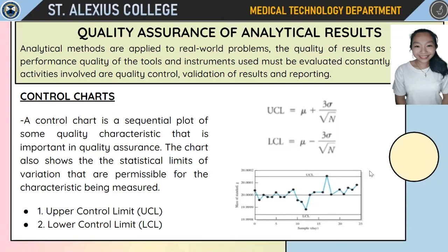A control chart always has a central line for the average, an upper line for the upper control limit, and a lower line for the lower control limit. These lines are determined from historical data. By comparing current data to these lines, you can draw conclusions about whether the process variation is consistent, in control, or unpredictable.